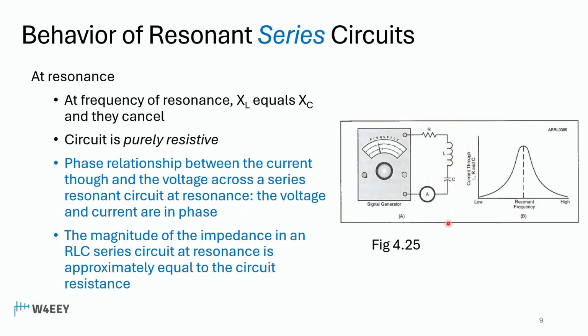The only way for the circuit to be purely resistive is if you hooked a wire up to the top of the coil and then shorted out these two components, L and C. Now the circuit would be purely resistive. And that indeed is what happens in a series resonant circuit.